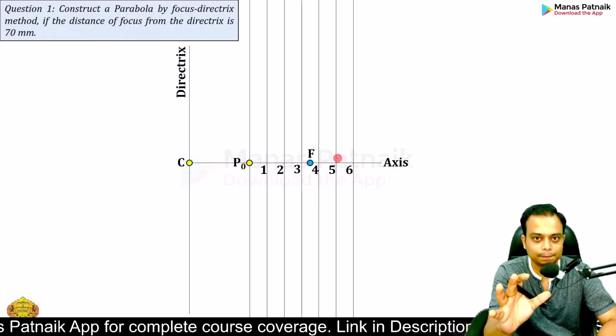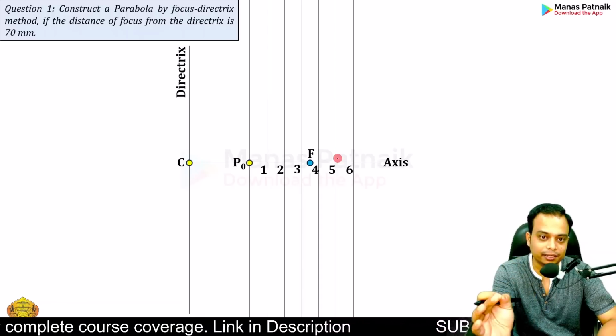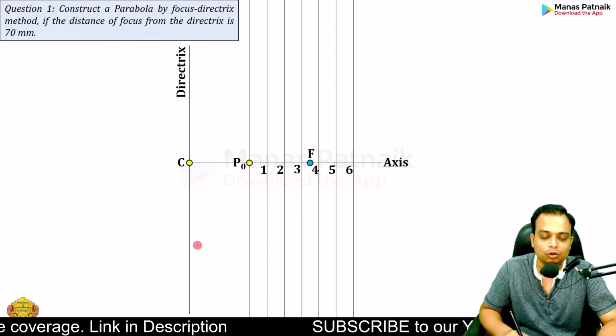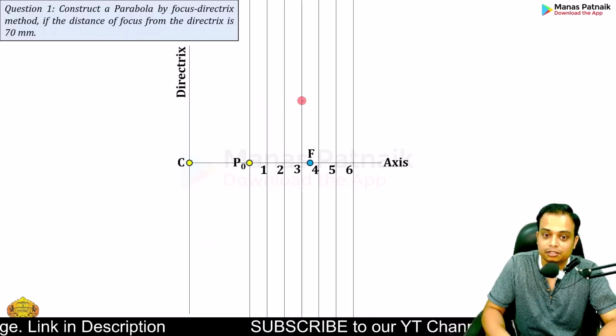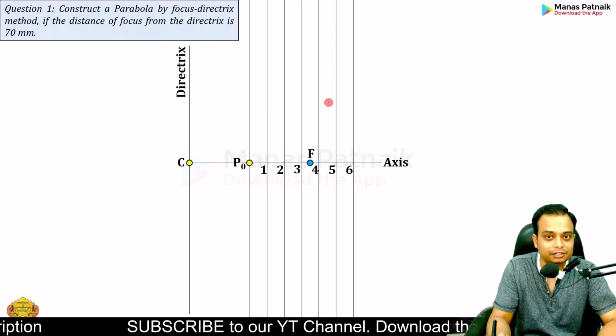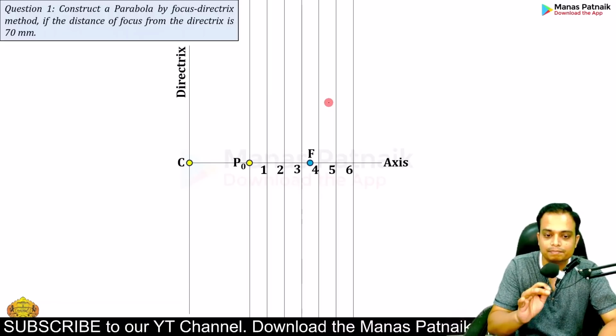Can you do this? Only the parabola will be bold and dark, or dark and thick. You can make this axis and directrix also dark, no problem. Whereas these construction lines should be very, very light, a little grayish in color. You can use a 3H or a 4H pencil for that purpose. Okay, now what's up?